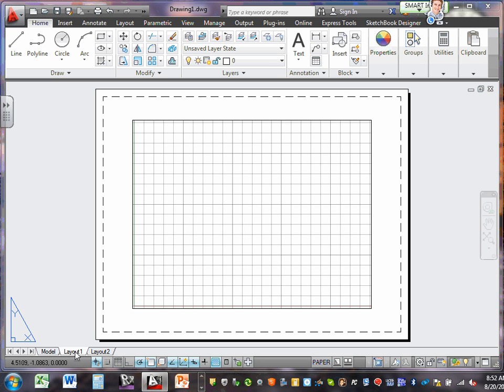So later on when you guys want to produce a product like this, 22 by 34, where do you think I need to set the page? They call it setting the page. You need to set your page in the layout, whatever size you want it. Right here, I believe this is an 8.5 by 11 page, so if we print it, it will print 8.5 by 11. So when we start printing, which is coming, the first thing we need to do is set up my page. What page are you going to print? 11 by 17, 8.5 by 11, 22 by 34, and so forth.